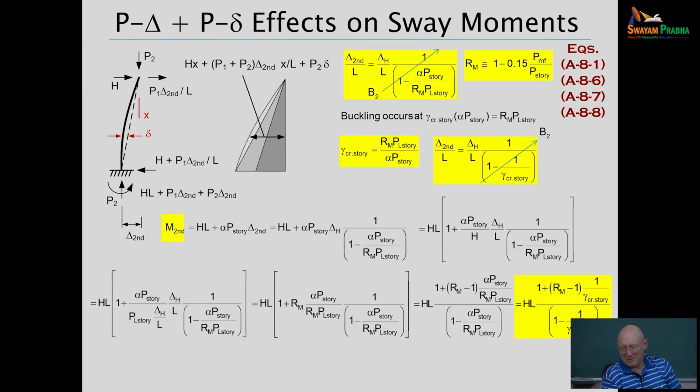All right. Well, that would be, I'll say, the fanciest way to write all this. But the AISC specification, LeMessurier knew this, but then as a practical design engineer, you say, okay, yeah, but I'm just going to use B2 also for the moment. I know that's conservative. So I have the same amplifier applied either to side sway displacement or to side sway moment. I'm good. Okay? But actually, that's a conservative approximation.